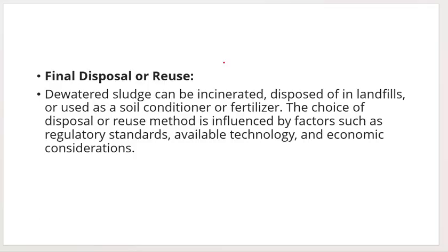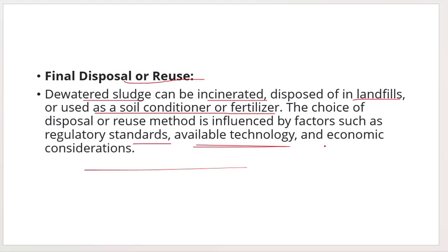Then final disposal or reuse. The waste sludge can be incinerated if it is highly toxic or highly infectious, or disposed of in a landfill, or used as a soil conditioner or fertilizer. The choice of disposal or reuse method is influenced by factors such as regulatory standards, availability of technology, and economic constraints. There will be regulations for using the sludge, and based on technology and economic considerations, we can use the sludge.